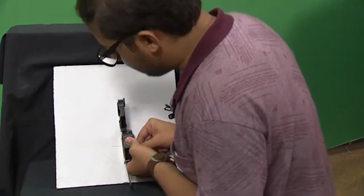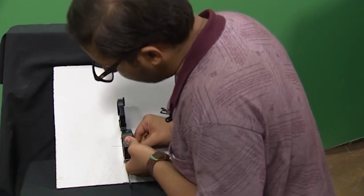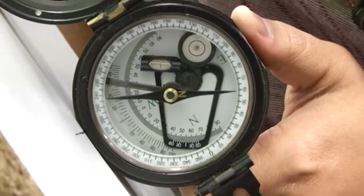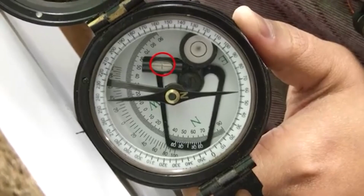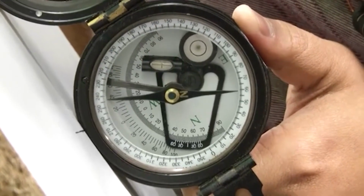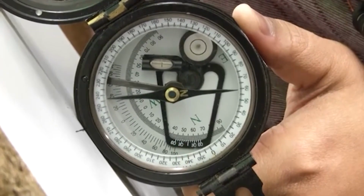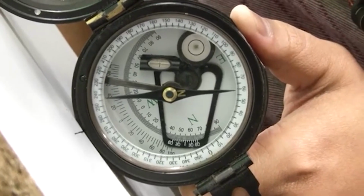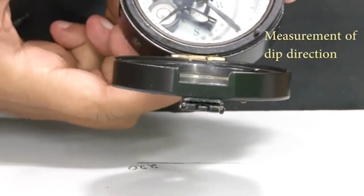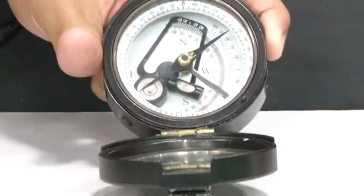Then we will adjust the back lever of the compass so that the bubble in the elongated level comes in the center. When the bubble in the elongated level has come in the center, the dip value is the value with which the 0 mark in the vernier coincides with the 180 degree graduated scale, and in our case the dip is 55 degrees.